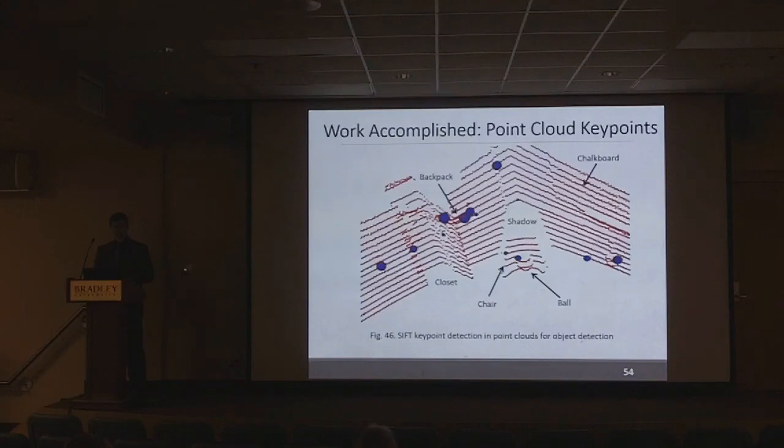However, there's a slightly different meaning for the key points. For an image, we're comparing the changes in color, but for this point cloud, we're looking at the changes in distance. So it's still detecting those objects by looking at their edges, where distance is changing. With this, I was able to determine the nearest object location by calculating which key point was located closest to the sensor, and using that coordinate location, calculate the angle and distance to that object. This was accurate up to 95%.